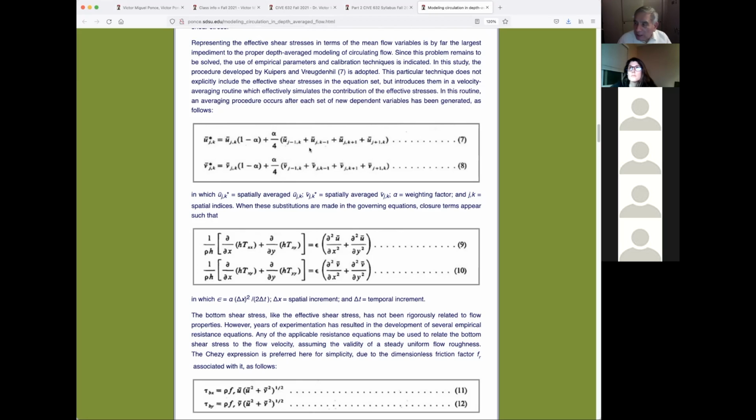We should also realize at this point that no problem out there that we care to calculate can live without some amount of diffusion. That's the function of the theta of the Preissmann scheme. Set it up to 0.55 and you'll get a little diffusion so that you can work out the problem.